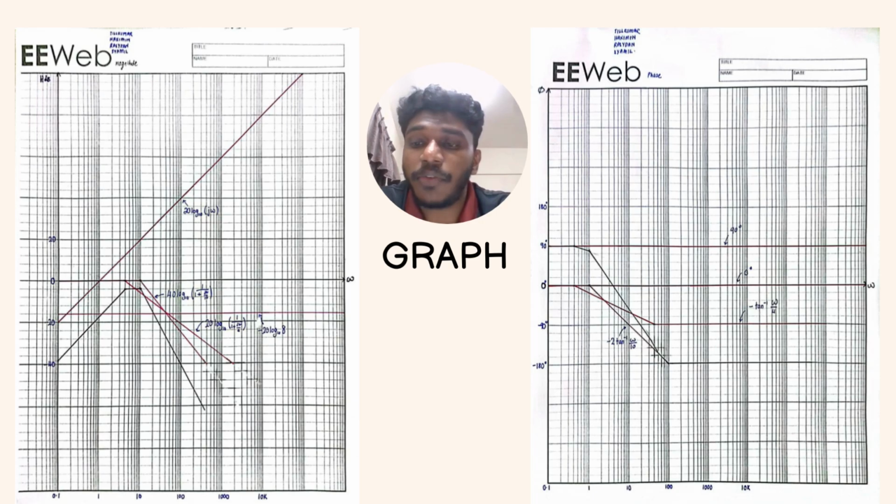For the 40 log 1 over 1 plus j omega over 10, it reaches until negative 40 because of the 40 value. Same as well for the 20 log 1 over 1 plus j omega over 4. Then we can see a straight line at the value of 8.